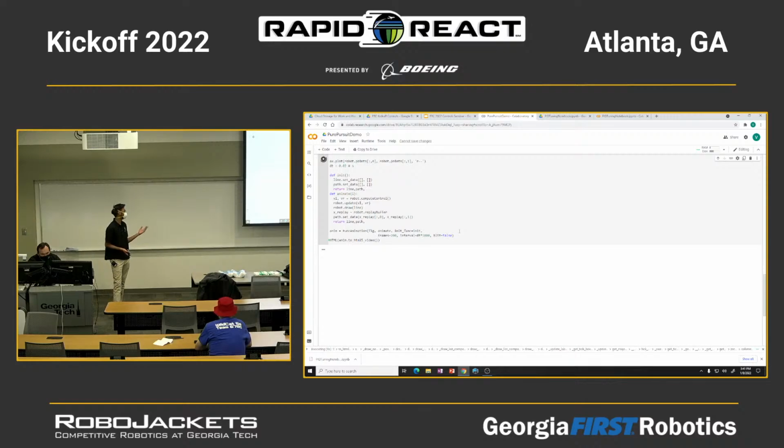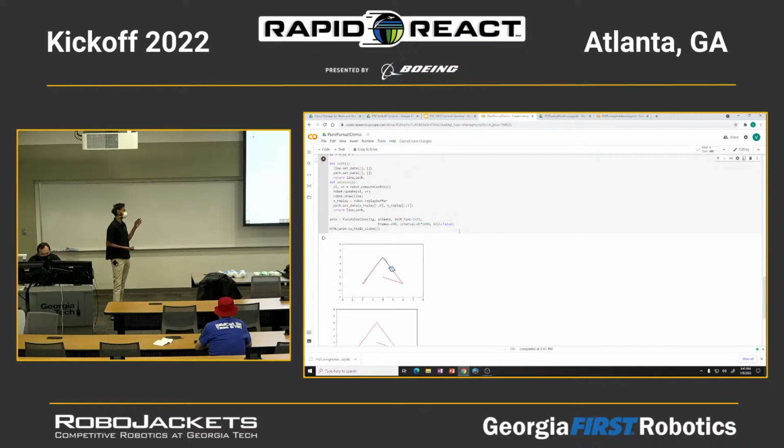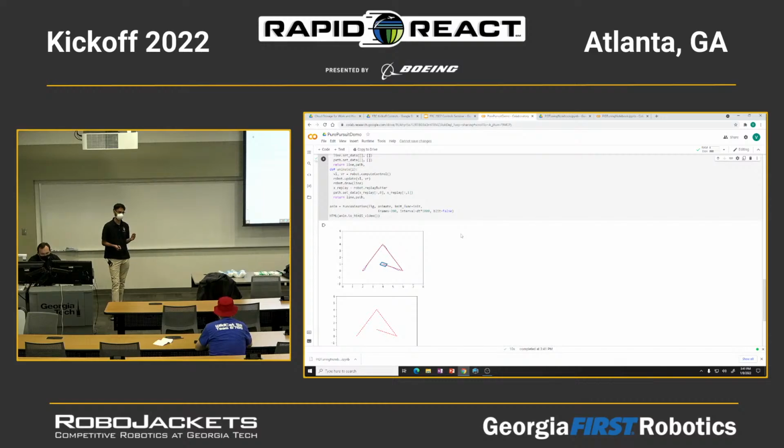As you've probably observed, since you can make tighter turns with a smaller look-ahead distance, you should decide the look-ahead distance based on how tight the turns are in whatever path sequence you want to make. Of course, a sharper turn means the robot actually has to slow down to make the turn. Otherwise, it would skid. So there is a trade-off here: the sharper you make your turns, the more you have to slow down at the end.